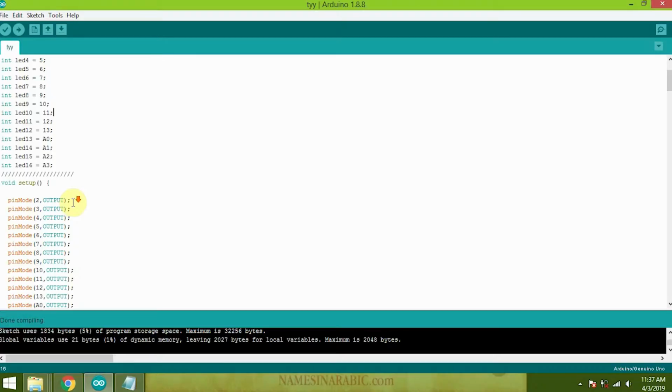Every Arduino sketch must have a setup function. This function defines the initial state of the Arduino upon boot and runs only once. Here we'll define the following. Pin functionality using the pinMode function. Initial state of pins. For this project, the initial state for LEDs is output, not input like sensors, because sensors can load data to Arduino.